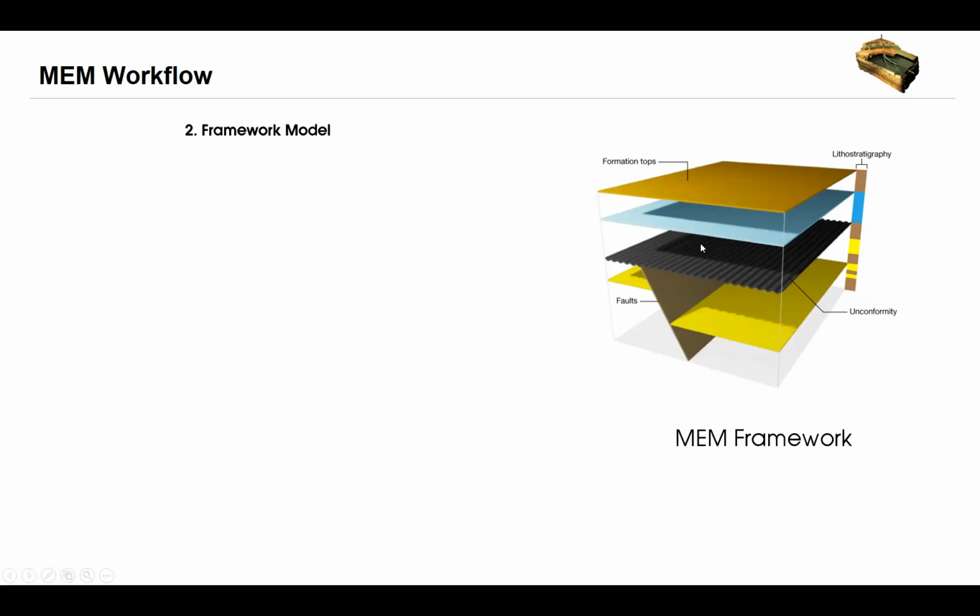So if the present day direction of minimum horizontal stress is in the fault dip direction, then the present day stress and the paleo stress might be similar. If the interval of sedimentation was long, the sediments above and below might not be similar. This observation anticipates the possibility that elastic and strength properties could be different across this boundary. The foregoing line of reasoning helps you to produce an internally consistent mechanical earth model.